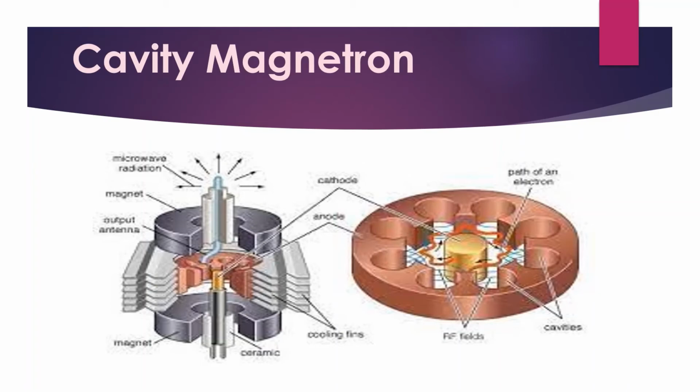In the previous diagram we saw there are two electrodes which will be taken out of the cathode, and when external DC potential is applied, this cathode will emit electrons, and with respect to the anode cavity, it will form an electric field as shown in this diagram. This is the electric field which will be produced when potential is applied to the cathode element.